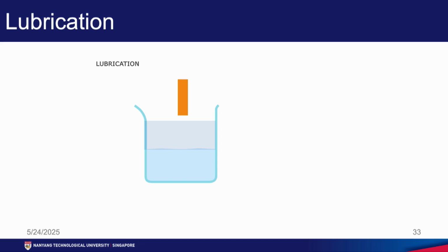In another coating method, they dip the disc into the lubricant, then they drain the liquid, the lubricant. The lubricant will be drained away, and your disc is coated with the molecules. Except for the lubricant layer, all the other layers are deposited by sputtering.